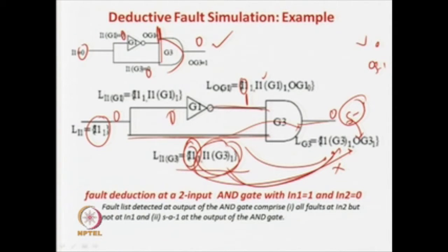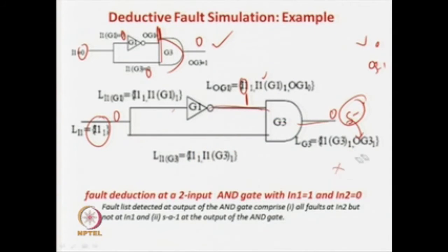Let us see why it is not propagatable, why it is not detectable. Let us study the case. In this case it is stuck-at-0. So, this stuck-at-1 is detectable over here. This is a 0 normal case, fault 1 case. So, 0 1 0 1. It is 1 0 because of this inversion, and your output will be 0 slash 0. So, this fault is not detected. This stuck-at-0 results in a 0 0 here, which is not detectable.